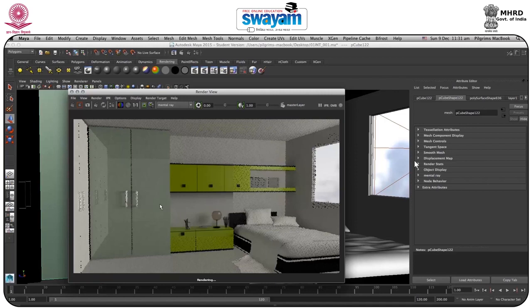And just do some much more tweaking in this thing. So we'll start working on tweaking. As you can see, this part is getting shadowed, which is good because we just used only one light. Now we will use 2 or more lights, and we'll look at the render, and after that we'll increase the amount of final gather and global illumination. As we have applied the blend, it's reflecting quite well.